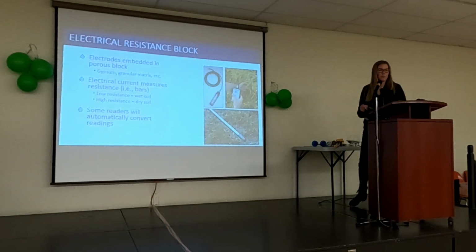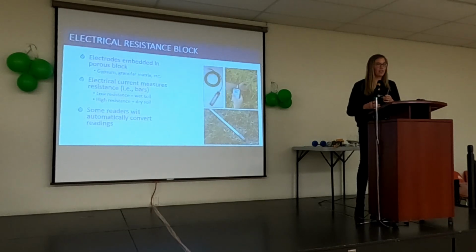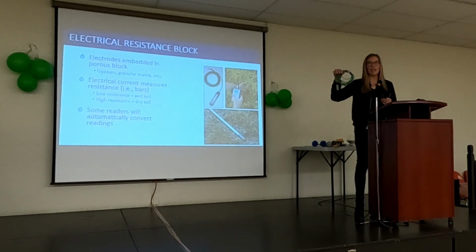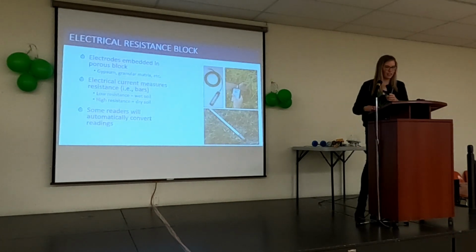So the next probe that I wanted to show was the electrical resistance block. So these give the same output as a tensiometer, but they are an indirect measurement of soil suction, because you're actually measuring the electrical signal rather than suction itself.